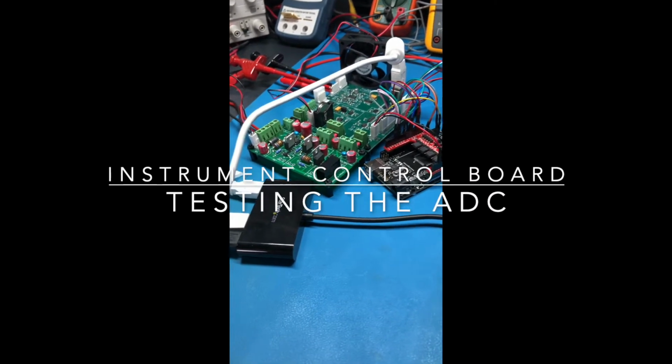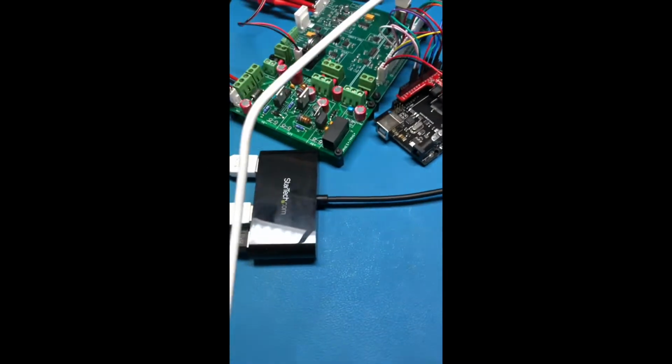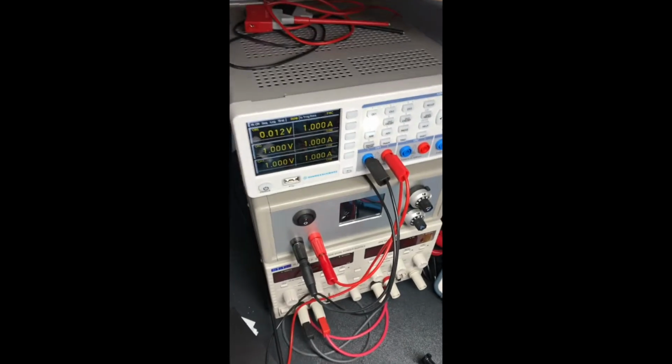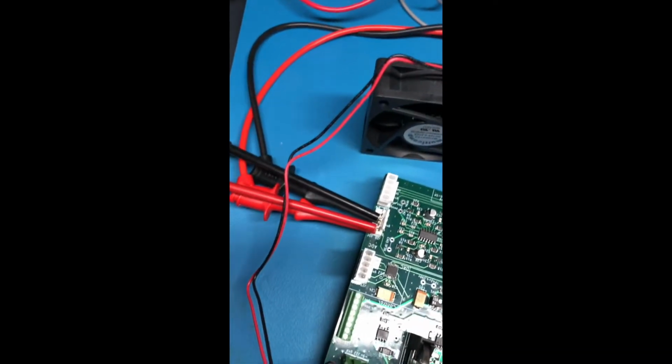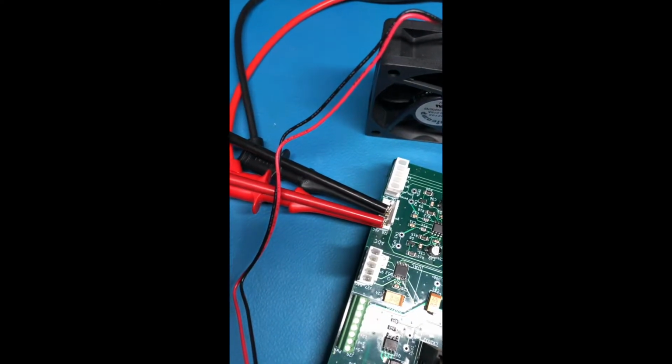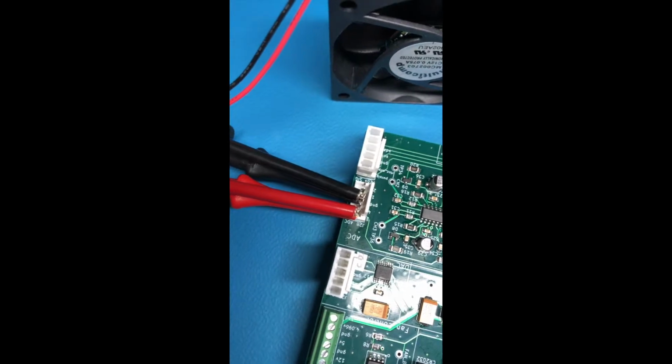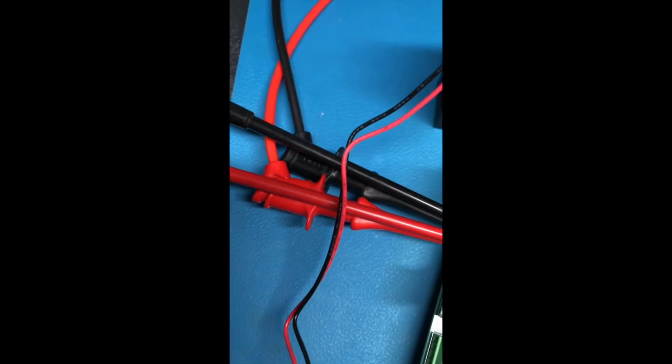So now we're going to test the ADC, and you can see this time we now have an extra connection on our USB which routes through to a power supply, and that power supply is going to be asked to generate voltages on ADC channel 3, and we have the multimeter reading those voltages.